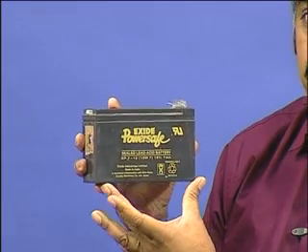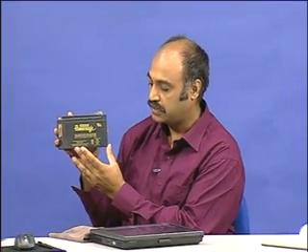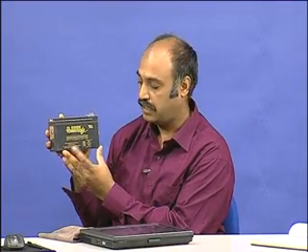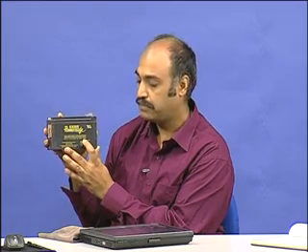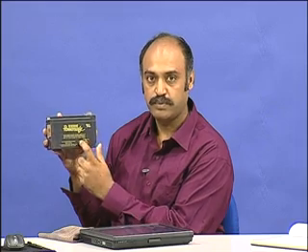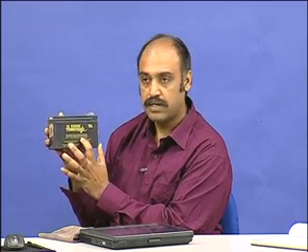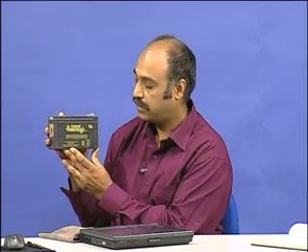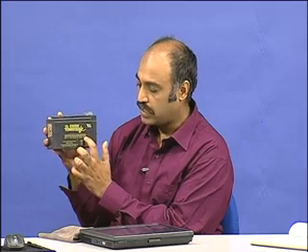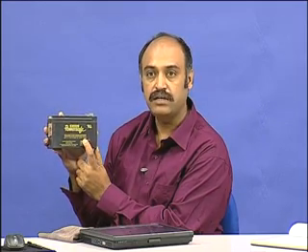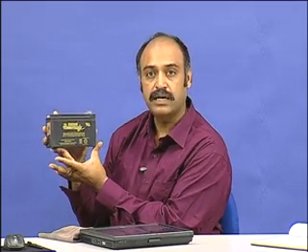Each battery has maximum discharge current capability. So, for example, if this is a C10 battery, let us say, then you can draw 7 by 10, that is 0.7 amps for 10 hours. So, which means 7 ampere hours, something like that. So these two numbers you will have to bear in mind while designing batteries and or choosing batteries. This 12 volt into 7 ampere hours turns out to be 84 watt hours. So 84 watt hours is the energy capacity of this battery.